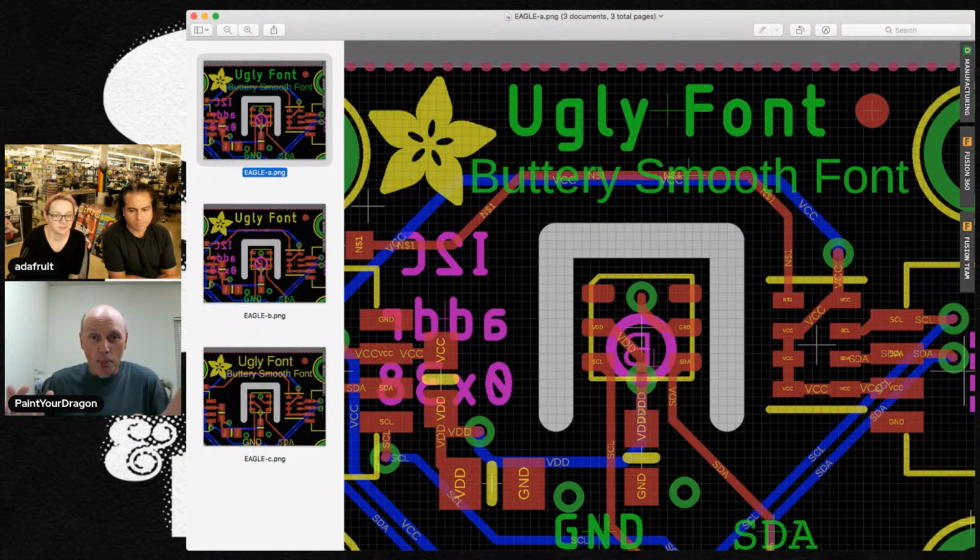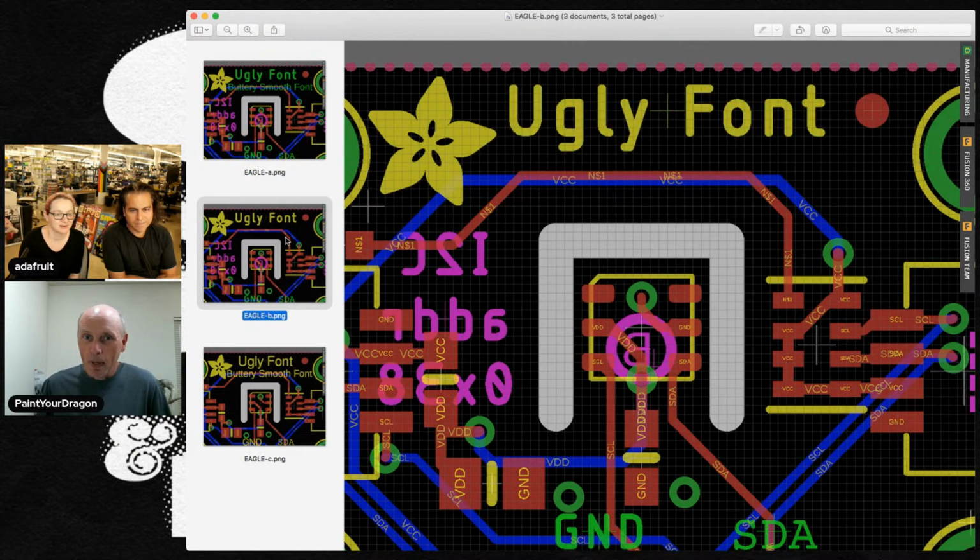And the proportional font is this beautiful, buttery smooth thing, and that's great, but it's only there to use in schematics. If you try to put it on the silk screen of a board, when you get the board made, it goes away. It auto converts to the ugly vector font. So sad. Everyone has the tragedy of sending it out with the proportional font, and then you get it back and you're like, wait, what?